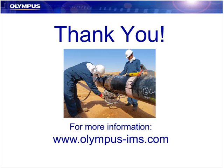How does the technique accommodate pipe thickness variation? I think this was probably asked before going over that slide. So basically there is some adaptation, especially for seamless pipe. We allow multiple setups that fit a range, and then we take a measurement and we apply the most suitable setup. They are all acquired at once, and we use that criteria or that setup information to do the analysis.